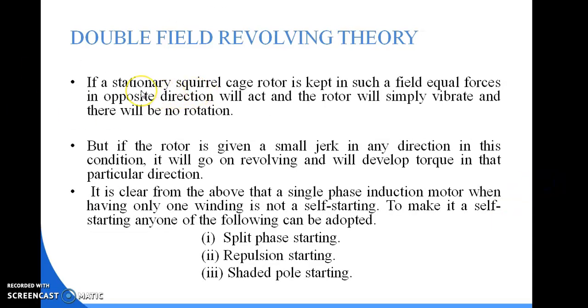So, if a stationary squirrel cage rotor is kept in such a field, equal forces in opposite direction will act and the rotor will simply vibrate and there will be no rotation. But if the rotor is given a small jerk in any direction, it will go on revolving and will develop torque in that particular direction.